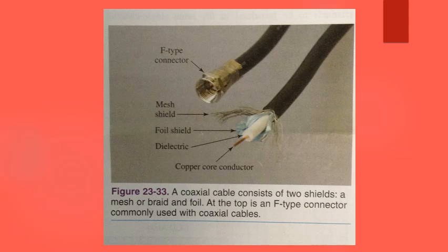Coaxial cable. The signal that is supplied by the local cable television company or through a satellite dish system typically connects to the initial receiver in the home from a single coaxial cable. Coaxial cable is designed to carry high frequency signals. The coaxial cable is designed to limit the radio waves generated from the center core conductor to the area between the core conductor and the shield. The shield will absorb the radio signal emanating from the core conductor when the high frequency passes through.